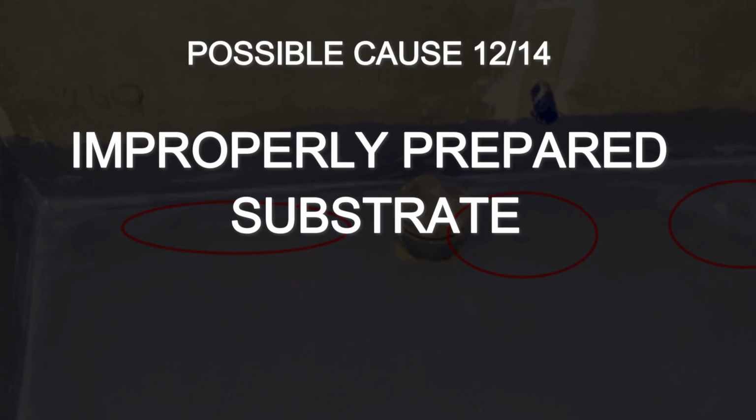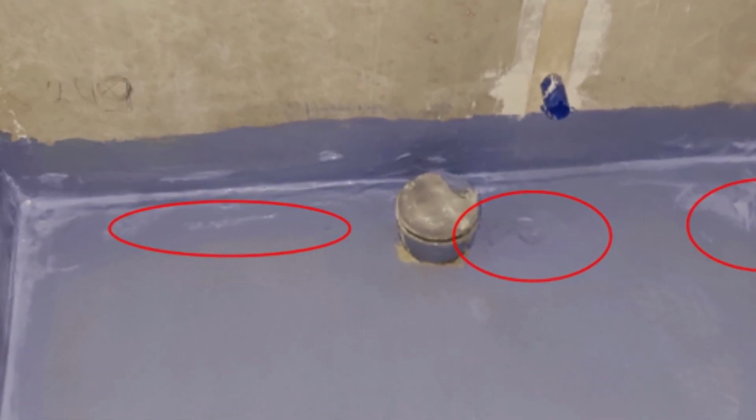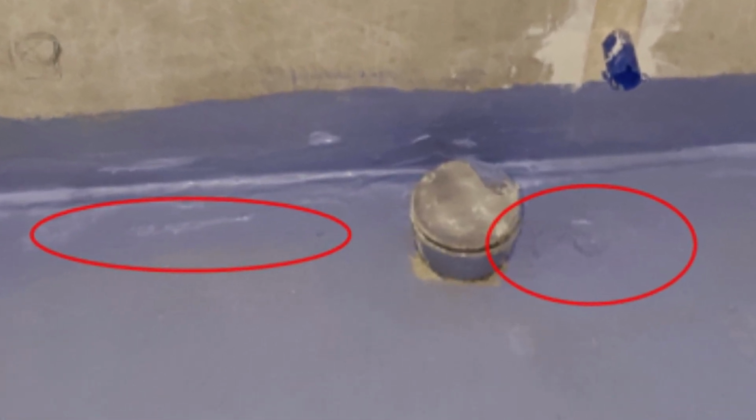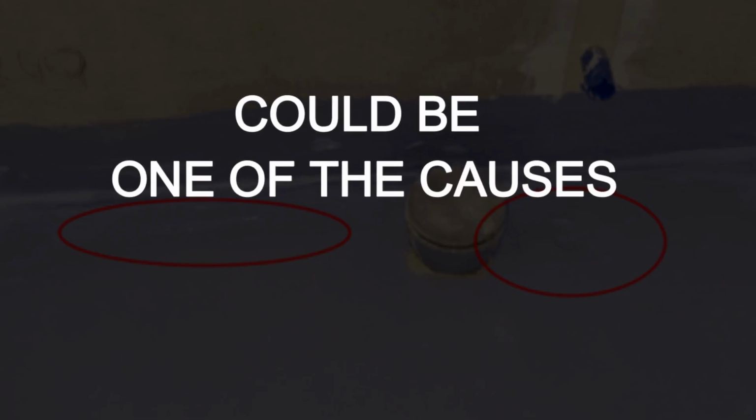The 12th version, improperly prepared base. Before applying waterproofing, it must be smooth, solid, clean, and primed with the appropriate material. In the photos, bumps, pits, and unevenness were visible under the waterproofing. Priming was also not properly documented in the records. In such places, the waterproofing may adhere poorly, become thinner, or be damaged.